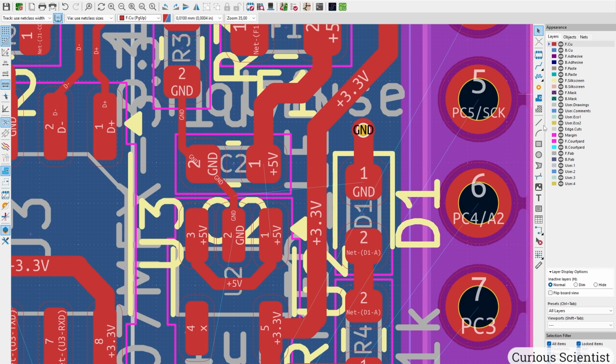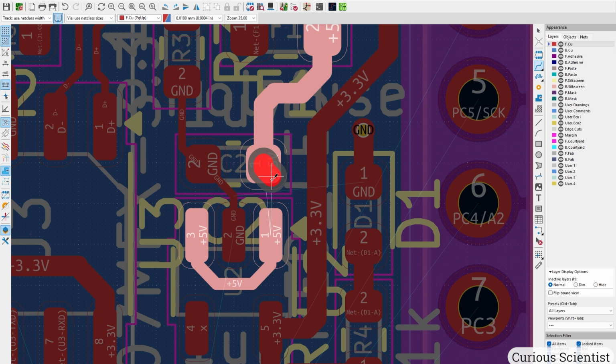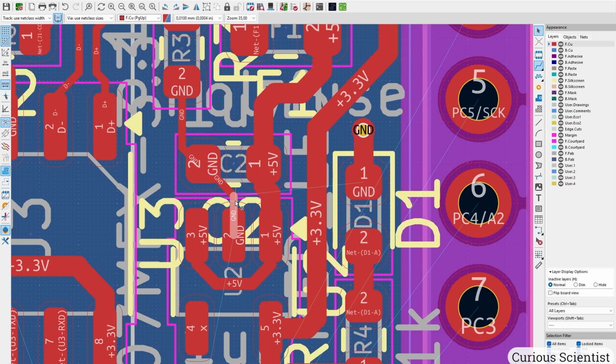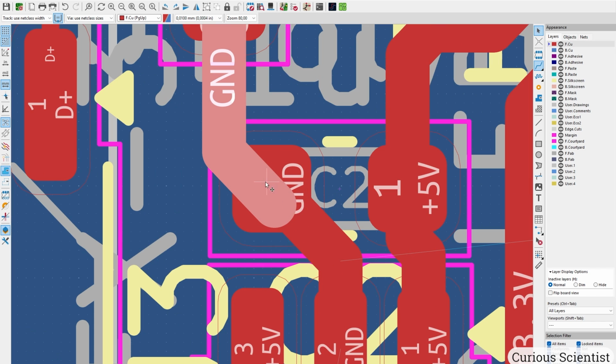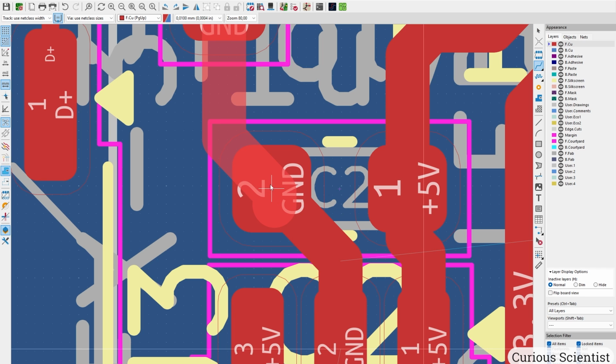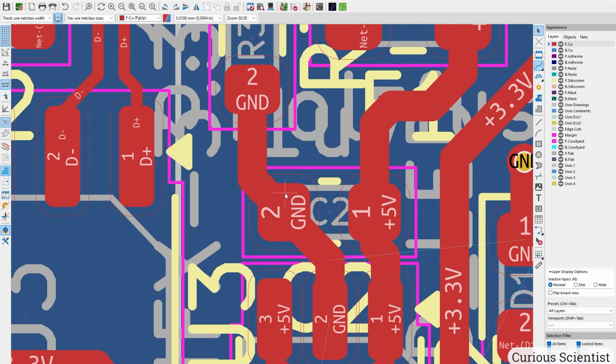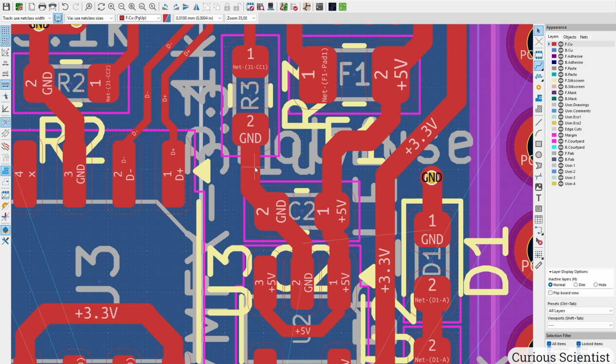And you can see that we missed a 5 volt trace here. So I'm just going to route it. So that's done. And then the ground also 0.5, 0.5. Again, could make an island or a fill zone, but it should be fine. So now this is routed together, but there is no ground.